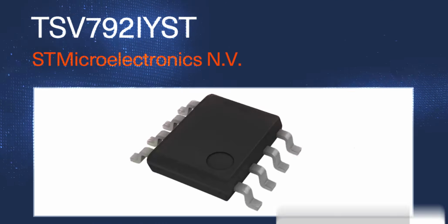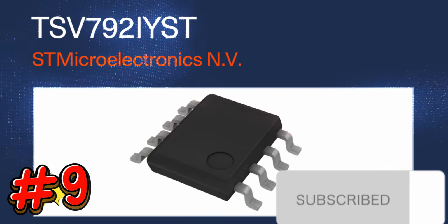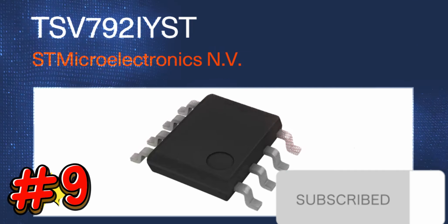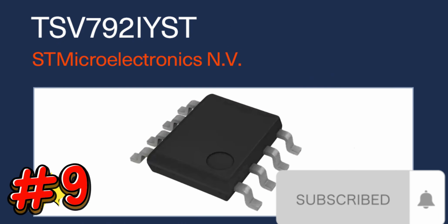Next on the list is STMicroelectronics NV. This dual op amp is a 50 MHz bandwidth unity gain stable amplifier. It has excellent accuracy provided by a maximum input offset voltage of 200 microvolts, allowing accurate amplification of small amplitude input signals.